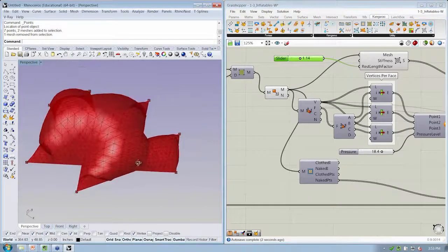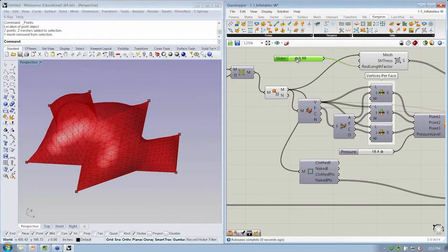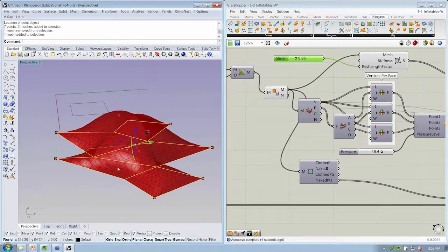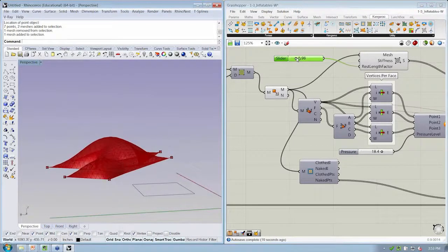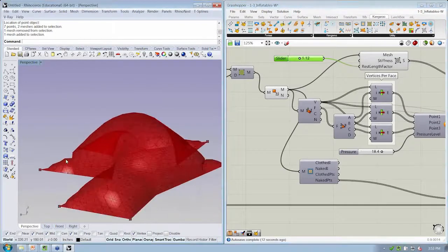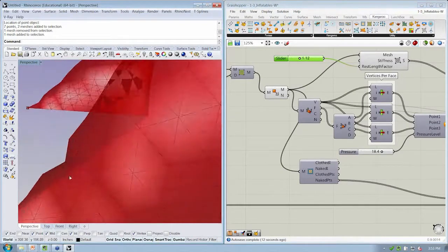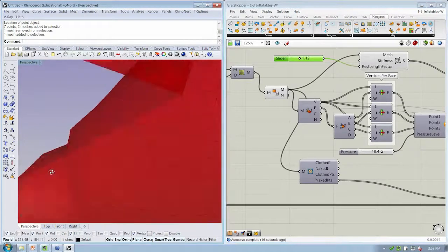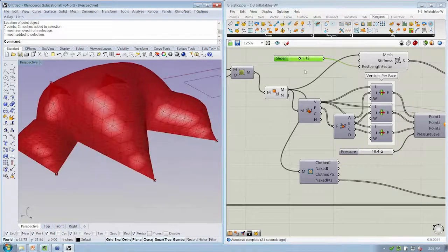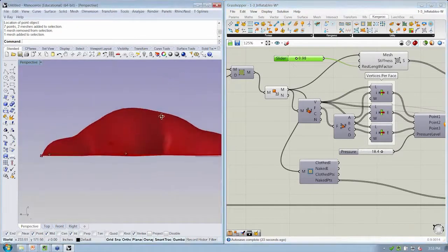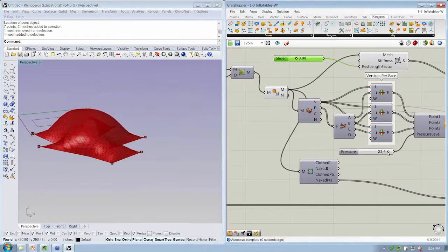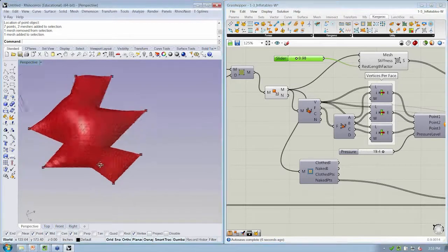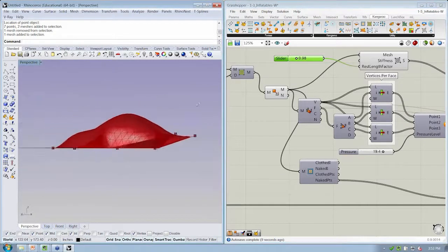All right, and now if we wanted to manipulate the initial shape, we're going to have to go back to changing the control points of our mesh. Now this is relatively interesting. Notice that if you go too far beyond 1, that's the situation I was mentioning before, where the mesh starts to kind of get a kink in it, right? So this wants to be about 1. If you want to make your inflatable volume taller, you're going to have to increase the pressure. But again, if you go too far, it can break, right? So you have to kind of calibrate that as you go. Okay.